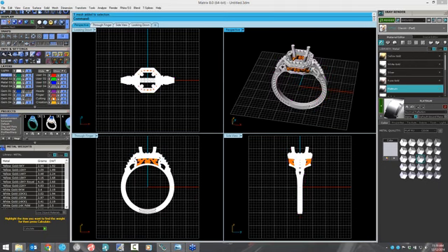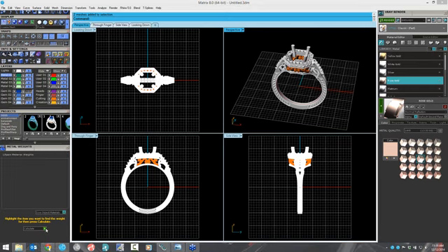Then I'll right-click these little scrolls and assign those rose gold. Now these know what material they have selected, and they know the specific gravity, and I can come down here and check Use Object Materials and hit Calculate. I need to select them first, though.